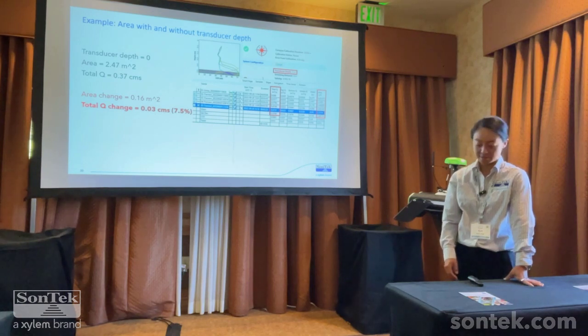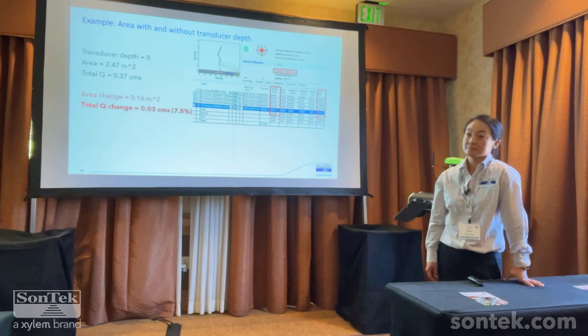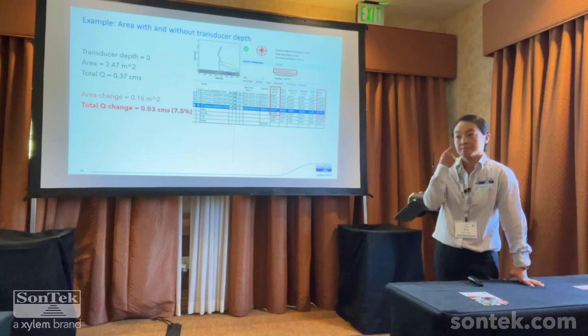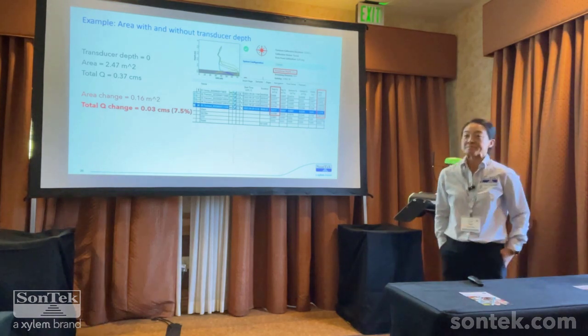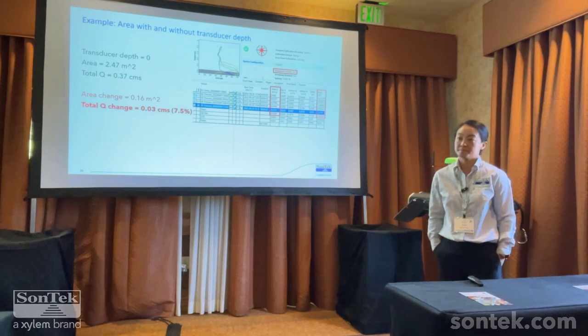You get all the depths and the lat-long, so if you have another program that you want to use to map it, you can. HYPACK's added value is just great visualization while you're collecting the data, and then you can create bathymetric maps and calculate volumes. There's a lot of processing features, and you can remove bad depth samples, which you can't do in our software. So you'd have to do that manually if you're mapping it out in some other program.